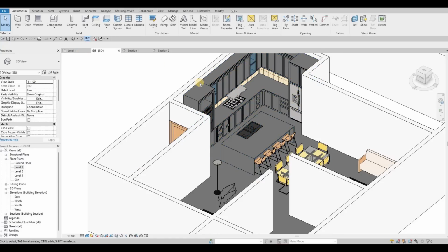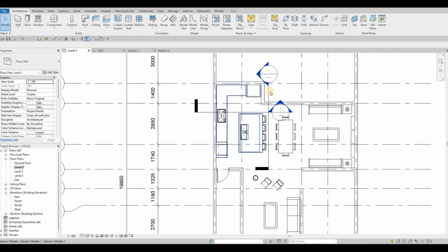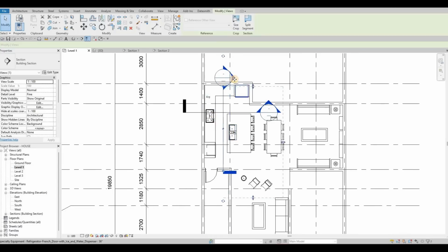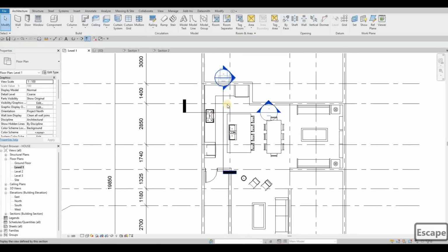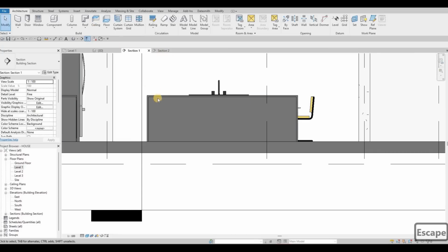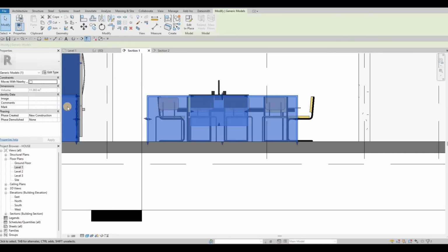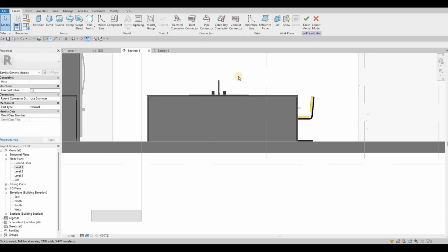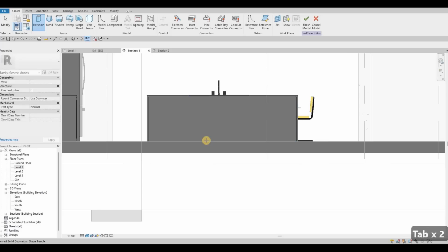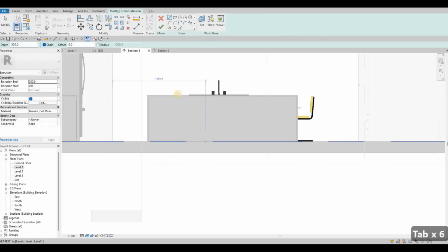So before we finish this, I just want to add something on this side so that everything looks nice and complete. So on this side, of course, we need some cabinets. So we're gonna do the same thing. So select this one, edit in place, and then extrusion, pick a plane, and then we're gonna select this face right here. So that's highlighting all of that, so that's good.